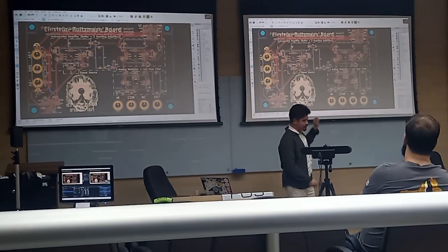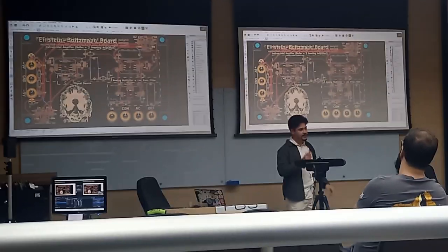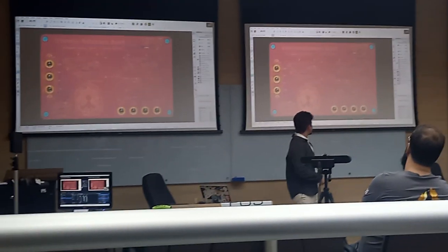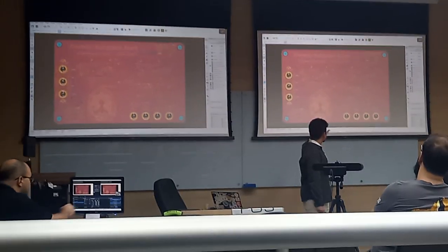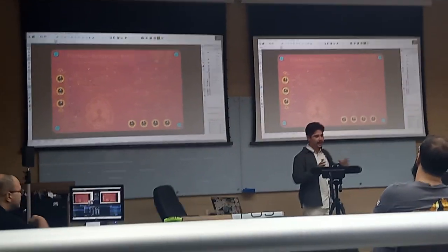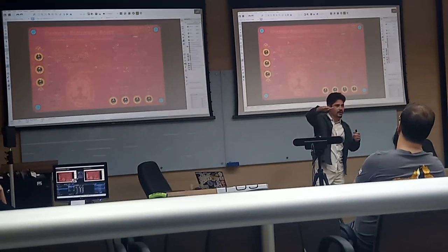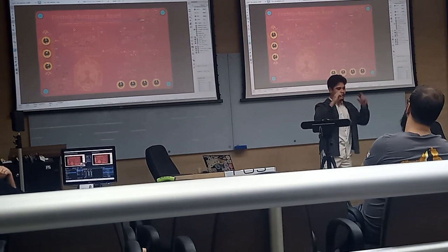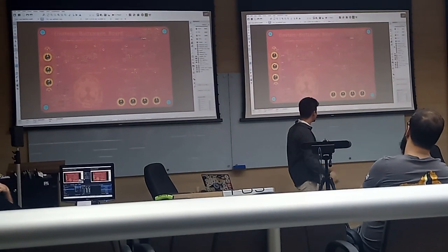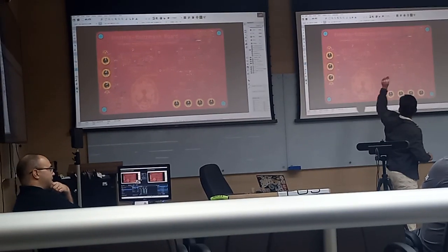You have this board, and with all of this made, you can, for example, make the ground planes. It's very important to circuit design. With the ground planes correctly drawn on the board, you actually have a big capacitor, because you have a ground plane on top, a metal plate on the top, a metal plate on the bottom, and a dielectric in the middle. For you guys that know electronics, that is a big capacitor. We don't want this. And to correct this, we can make little short circuits on the board.